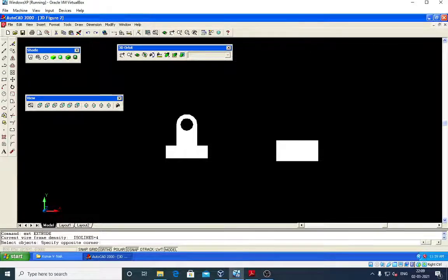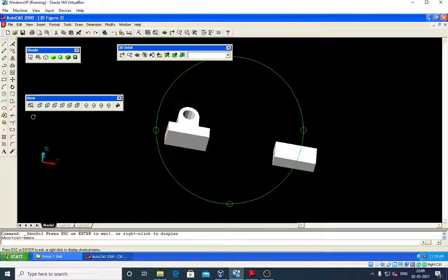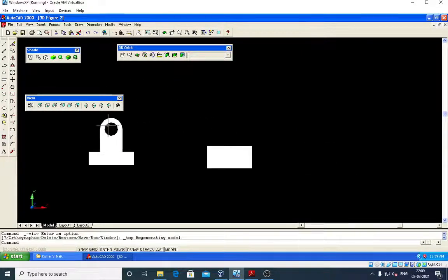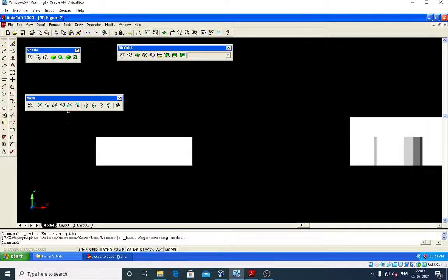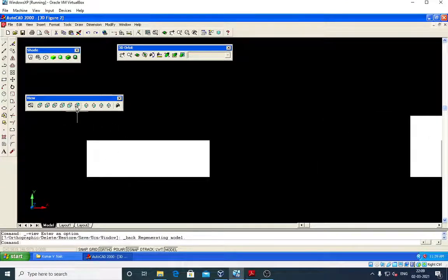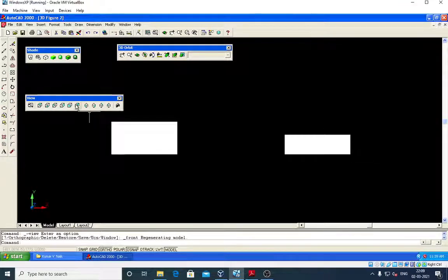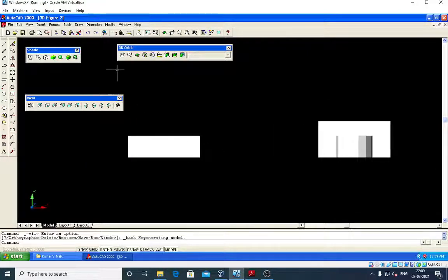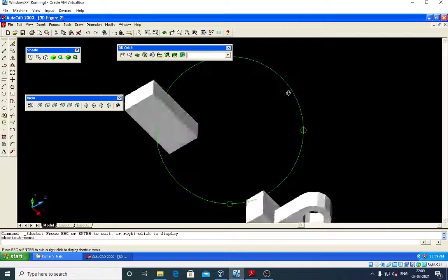EXT, selected object, enter. Height it is asking, specify 30 mm. So angle is 0. So now it has been extruded. Look at this, right? So it has been extruded. Now I will take this part, or front view or back view we can take. As you know, if I rotate this, there you will come to know how it looks.